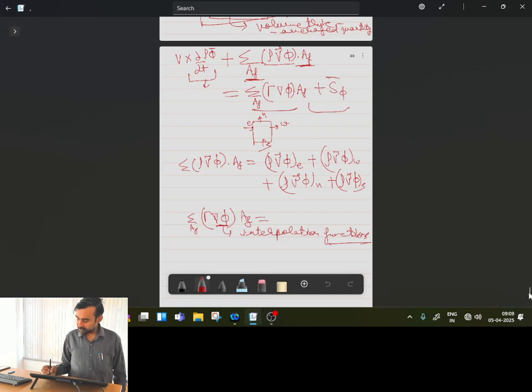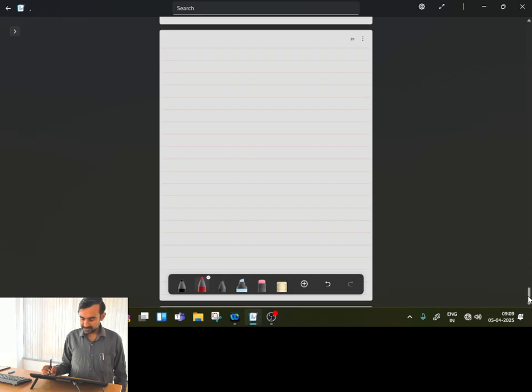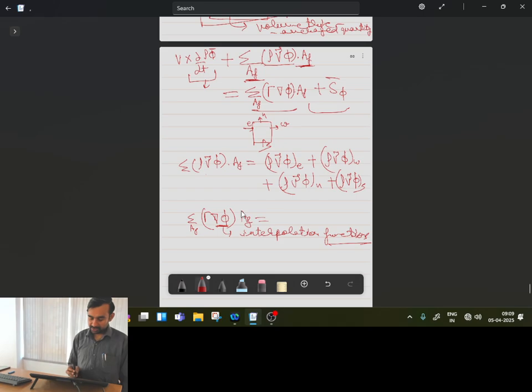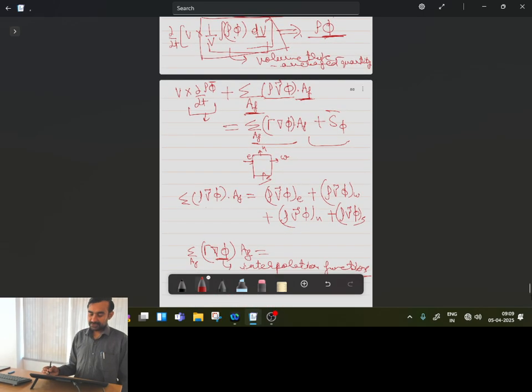Okay, good morning. So, we have been discussing the finite volume discretization of the scalar transport equation. And there I explained how our different partial differential terms can first be converted into algebraic terms. So we saw that we have one temporal term which involves the cell or volume averaged quantity phi bar.